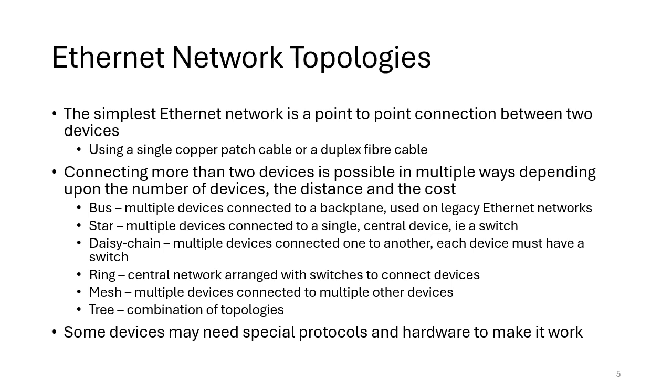But with using specific protocols, you can create a ring type network. Often this is used as the backbone between multiple devices. It can also be used in fault tolerant networks. And in this case, we have a central network with switches which are used to connect the devices. And those switches have to be both supporting the ring topology as well as whatever ring protocol you're going to use.